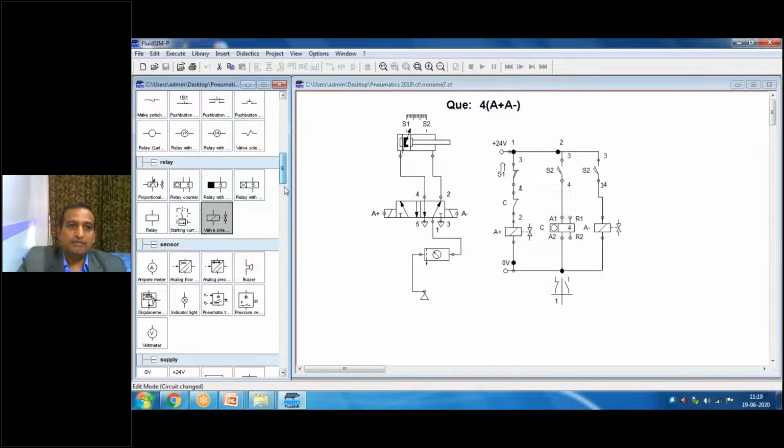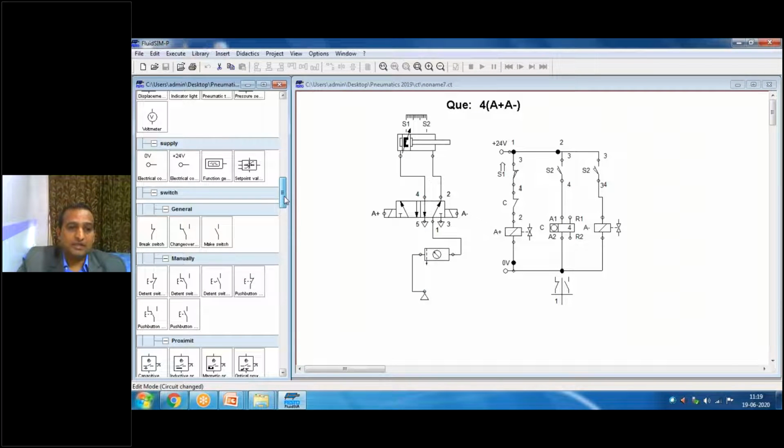Initially I'll show it manually. I can use a push button, because resetting a counter is very risky. If you hold the reset button, the counter is dead. It should be only a fraction of a second. If you hold the reset button, the counter is dead. So to reset this, use a push button.